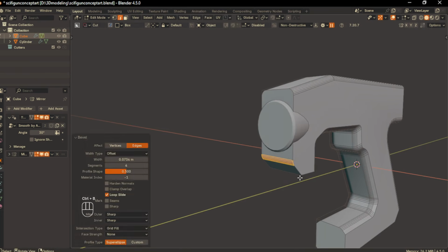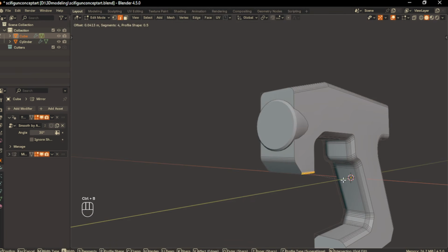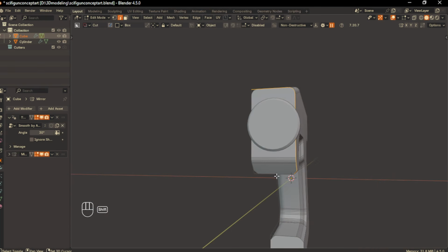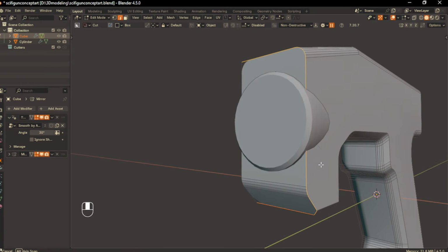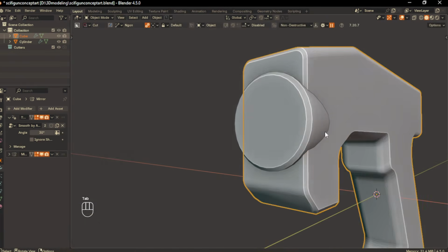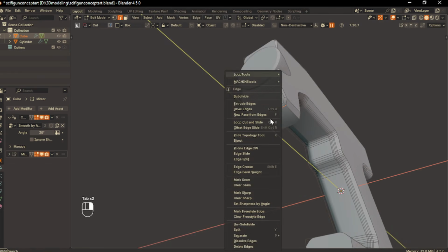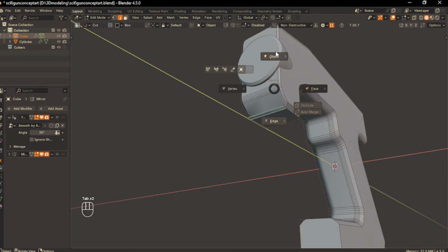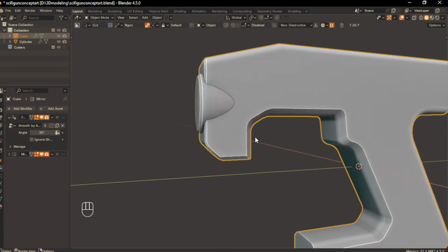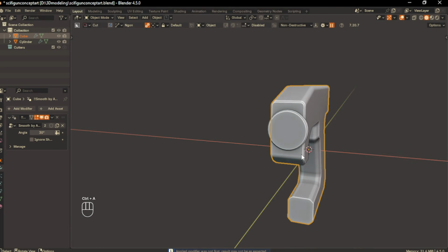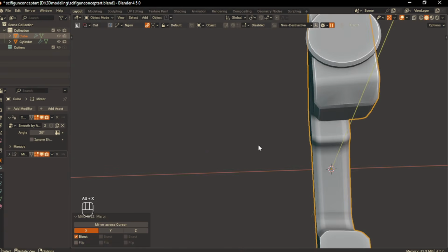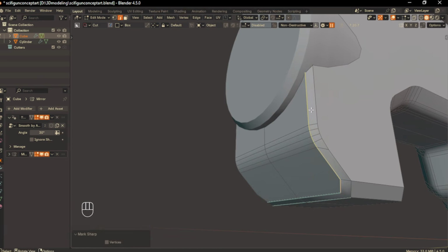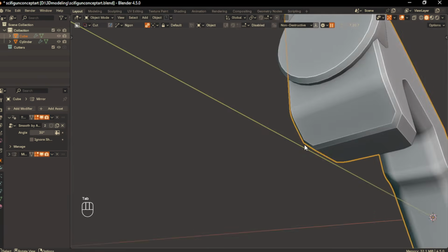Let's add a little bevel here. Then chamfer this one. And now I'll select all loop edges and run a small chamfer across them. Bottom shading looks off. Okay, let's just manually mark these edges sharp. And I see maybe the mirror's problem, so we just apply the mirror first. Done. Now reapply the mirror modifier there and back into edge mode. Select everything and mark sharp again. And yeah, that cleaned it up.